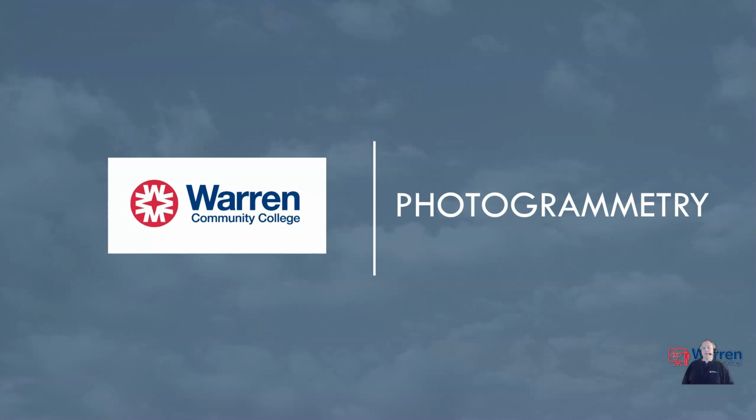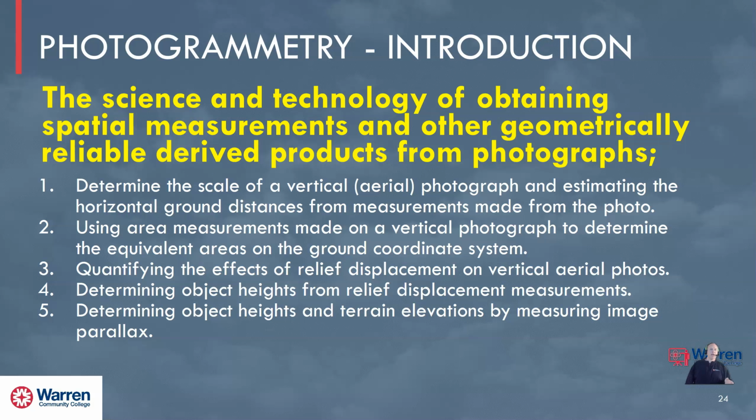But let's talk about photogrammetry, this concept, a little bit. So here's kind of your introduction. Photogrammetry is the science and technology of obtaining spatial measurements and other geometrically reliable derived products from photographs. So what we're trying to do is take that 2-dimensional photograph and put it into a geometric and geographic context. So you can determine the scale of a vertical area photograph and estimate the horizontal ground distance from those measurements made from a photo. So how many inches were those 2 cars apart? We could measure to a degree of error. There will always be error, but we'll begin talking about, even in this video, how we diminish that error.